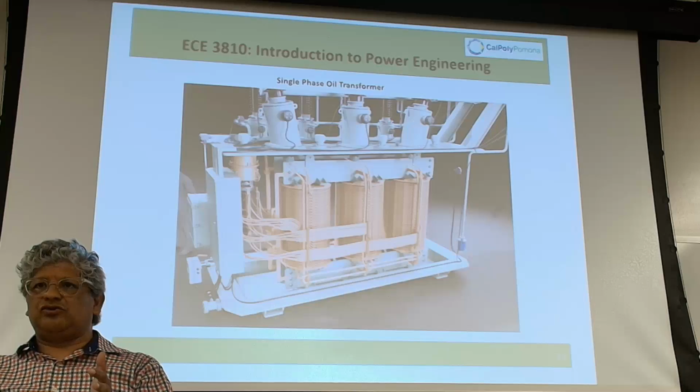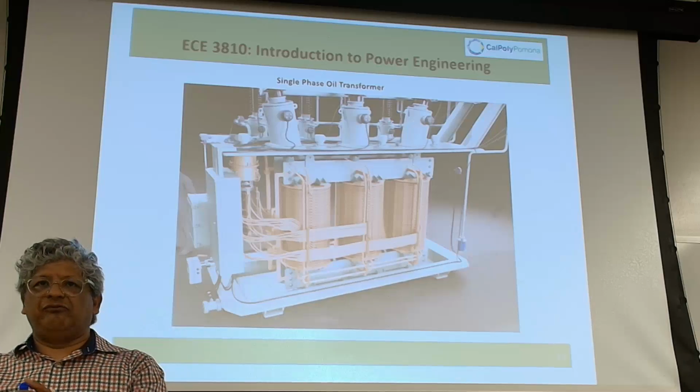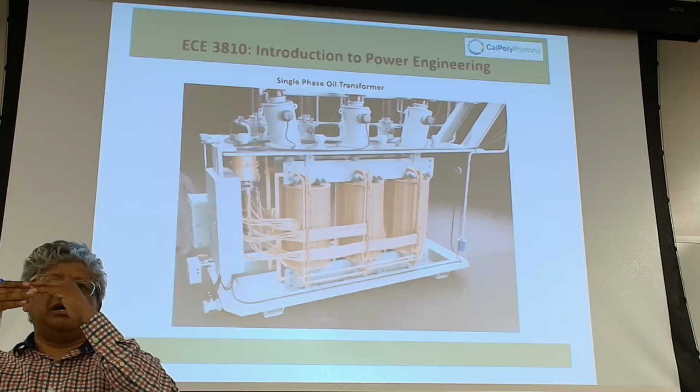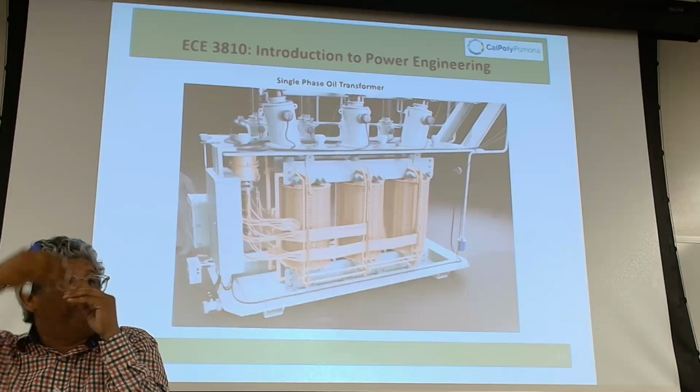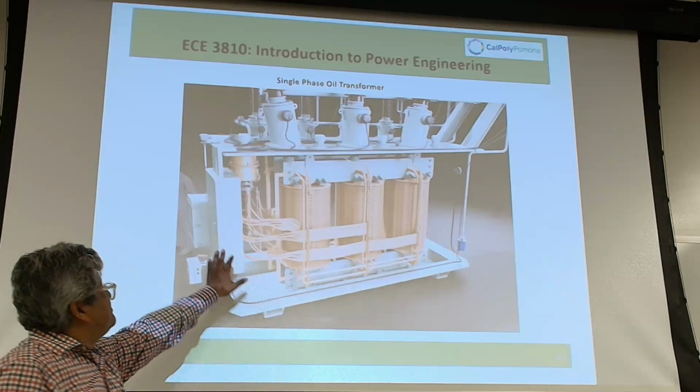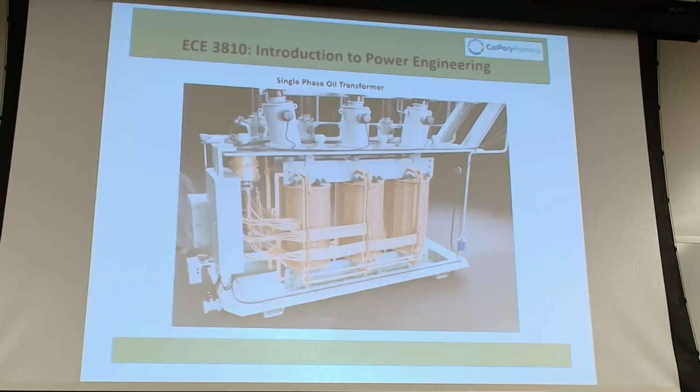The transformer is set to function within plus or minus a certain voltage, and when the voltage is depressed, the tap changer goes. There's a motor and it increases or decreases the voltage by the percent that the transformer was designed for. Believe it or not, that is one piece that transformer manufacturers don't manufacture. They buy it from the best company, called Reinhausen. It's a company in Germany. There's a town Reinhausen, and that's what most transformer manufacturers buy that one little piece from.